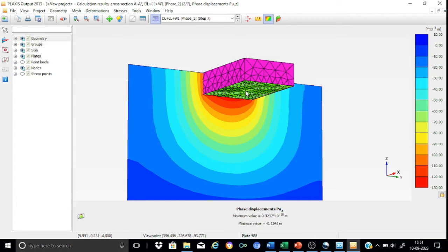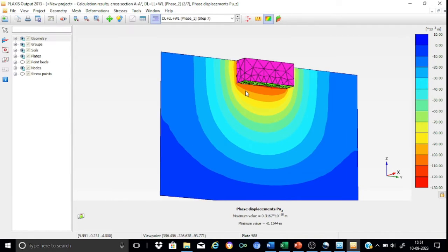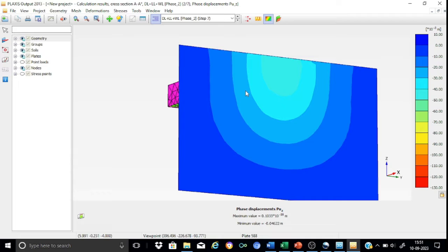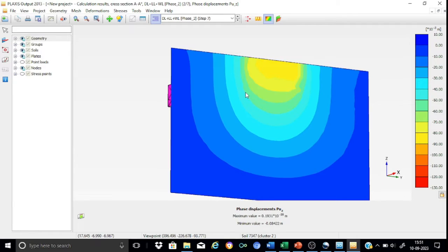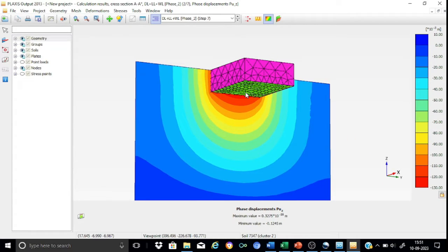Okay, so just press it and you can see that Control minus, if you see it is moving across this, and once it comes, you will find that the displacement contours drastically reduce. So within the raft, we find that we have settlements of the order of a maximum. You can see that this maximum settlement comes almost at the mid depth, is 124.5 mm. Okay, fine. So we can also inspect the so-called vertical stresses here.